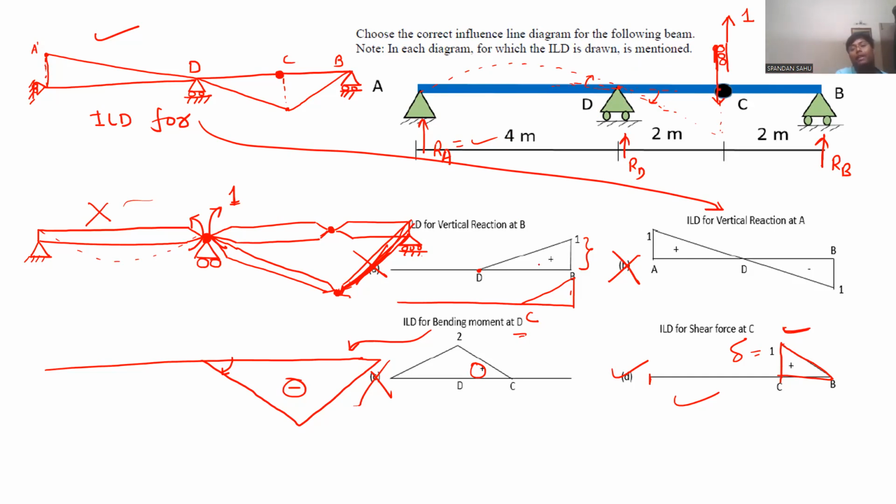That will suggest that the elastic curve between ADC, when you are pulling it down, will take a non-linear path, due to which the ILD won't accommodate the non-linear part for a linear, elastic and statically determinate structure, so all your points for that part become 0 and you are ultimately left with the BC region having a rectangular domain with a lift of 1 at point C. You got it, right?